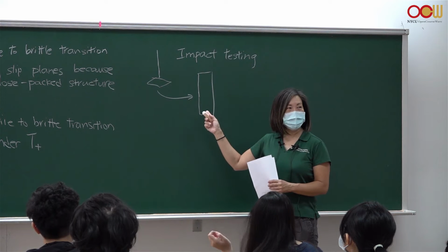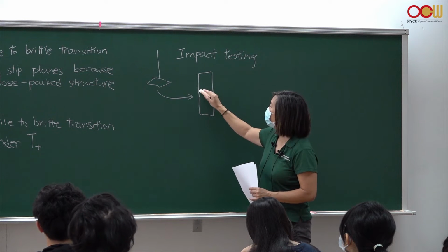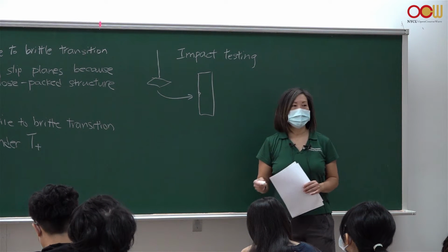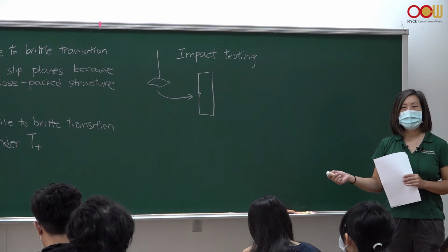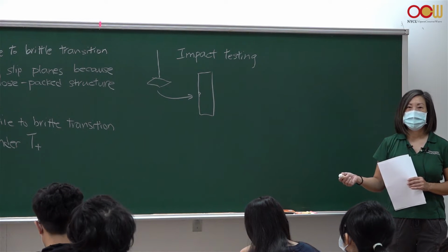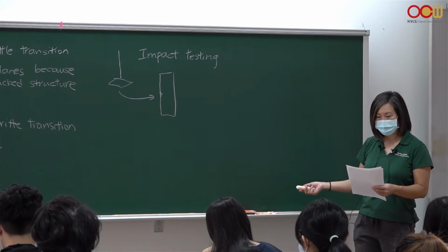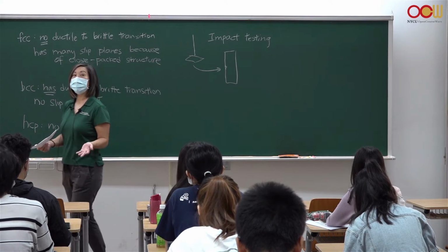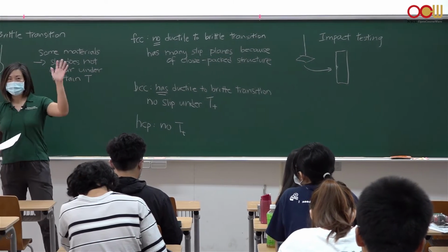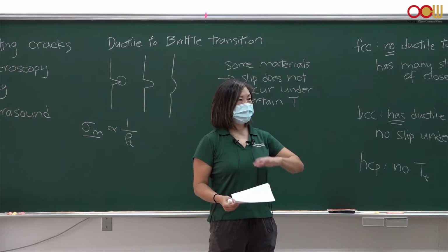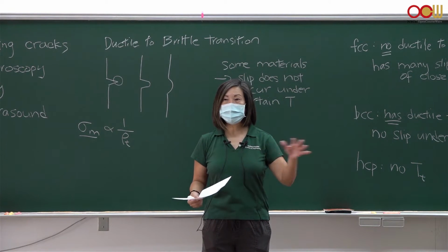So you might say, this is a piece of material with no cracks or very few cracks. So you etch the surface, you polish it, you make sure it's very, very smooth. And then you measure the impact testing, that's your fracture toughness, the amount of energy it takes to break this piece of material. Then you start to introduce different size cracks to this material, and then you test it again to see how much energy it takes to break, right? So that you can see the influence of cracks on this particular material. So that's something that's done very commonly in a materials testing lab. So in a material testing lab, you'll see a tensile tester. That's always there because you could get the stress strain diagram, and we know that you could get a lot of information there. You will probably get a 3-point bending test.